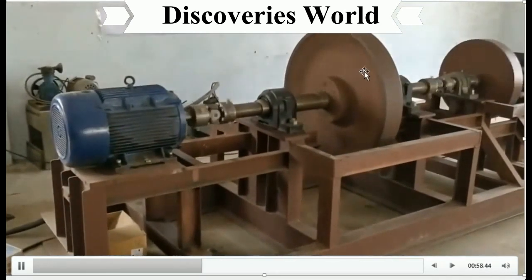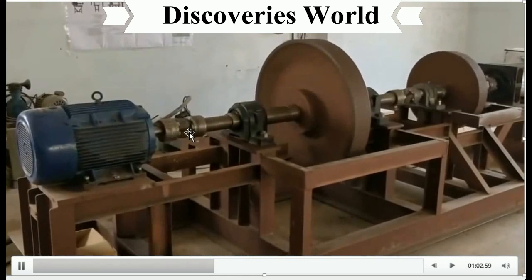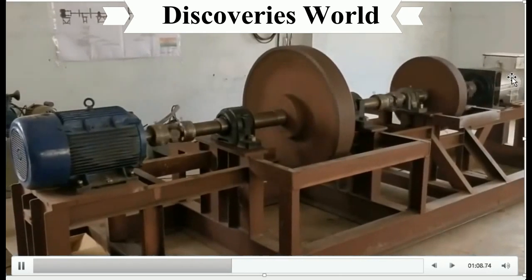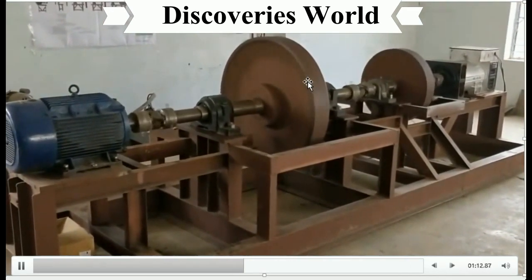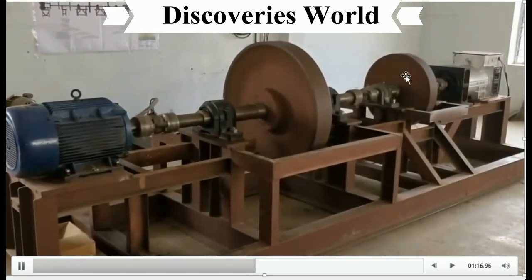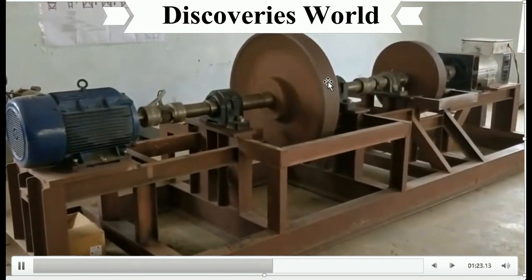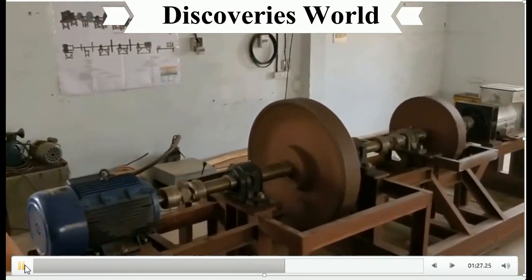What it means is that even if you cut off or disconnect this immediately, the flywheel can still be turning, and that means that the generator can still be producing. So when the flywheel is at high speed as it is now, and you disconnect the electric motor, it does not affect the production rate of the generator because it already stored the movement. That's what I mean by store it.